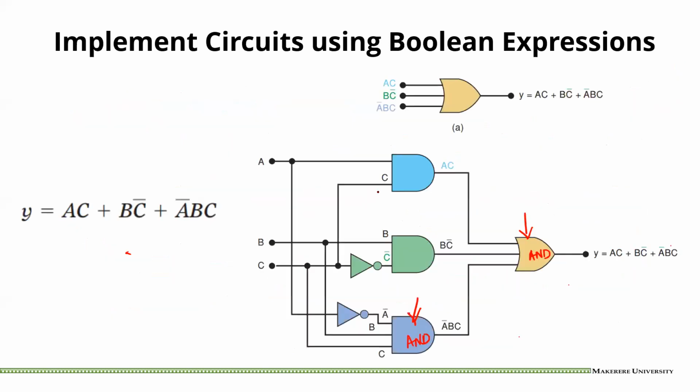And if you look here now, you have 1, 2, 3, 4, 5, 6. So instead of 7 or 8 gates, you can actually use 6 if you have these larger input gates. So maybe if I bring a question like this, I would be able to tell you whether you can use only strictly 2 input gates or you can use larger input gates. That one I would have to specify. Otherwise, the circuits would probably look different, which is something we want to avoid.